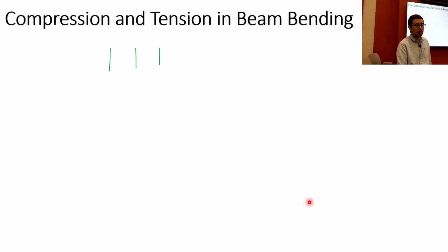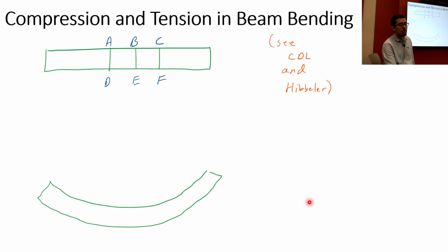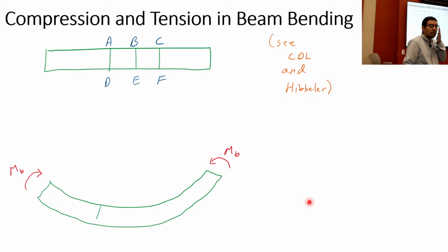In this case, where we've got our undeformed beam and then we deform it, which part of the beam is in compression, which part is in tension? The top part is in compression. Underneath the neutral axis, or the longitudinal axis, is going to be in tension. We know this: sigma is equal to negative My over I. So we're still following those relationships.